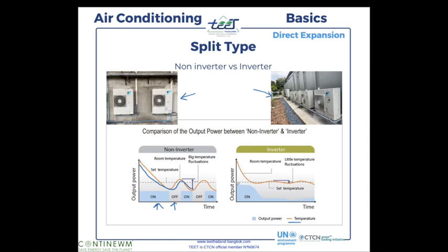With an inverter, the compressor is on full speed at the beginning, okay? So it consumes full power. The temperature goes down fast, okay? Then after you get near to the temperature setup, the temperature setup in this line, okay? You're getting near, so it starts to reduce the speed to save energy, okay? So the speed goes down, so the power consumption goes down. The speed of the temperature decrease goes down, okay?